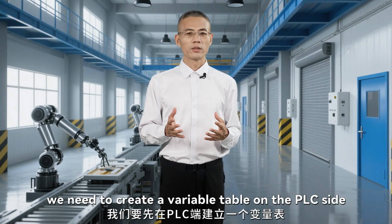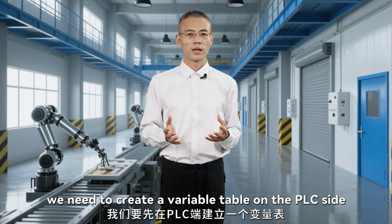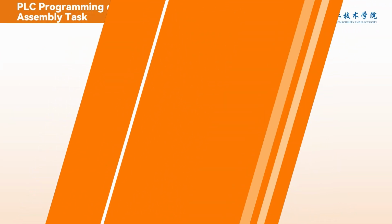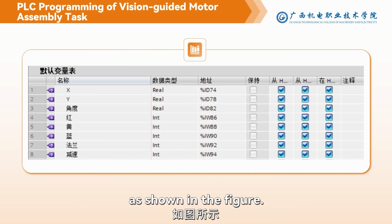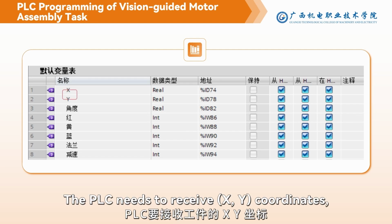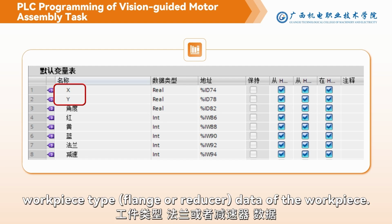Next, we need to create a variable table on the PLC side to receive the data sent by the camera, as shown in the figure. The PLC needs to receive the X, Y coordinates, deflection angle, color, and workpiece type data of the workpiece.